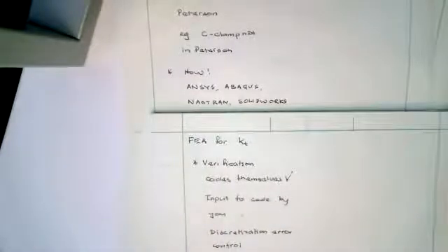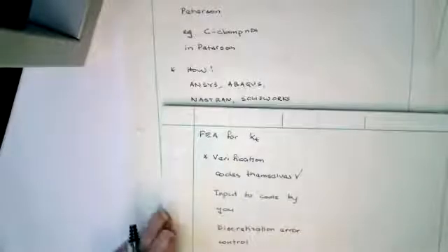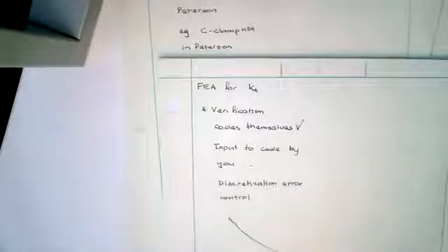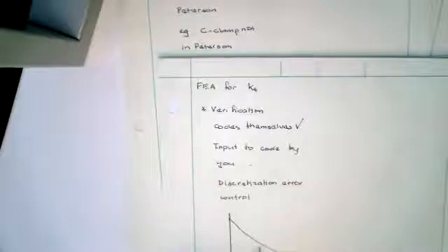And these things all involve approximation. There's an underlying approximation which occurs within elements. And when you make an approximate, it'll differ from the actual function. And as you refine your mesh, hopefully that goes away. We have to spend some considerable time talking about how to do that. But here's sort of what I mean by discretization here. Suppose I have a function that looks like this. Then if I approximate it with one constant, I would take the middle value.